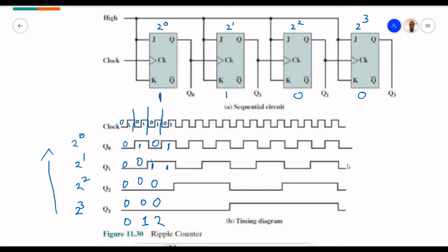So once our clock pulse changed here, we go back up to 1. We're still at 0 here, we're still at 0 here. This is 3. We have our next clock pulse change. So this falls back to 0 at Q0. Q1 also falls to 0 because we've had a complete up and down pulse here.